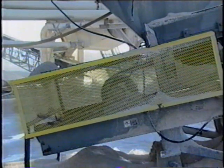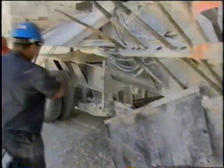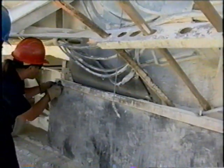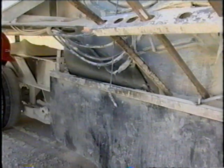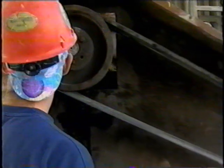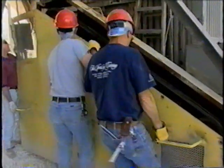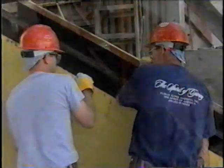Guards protect workers from exposure to moving machine parts. Serious injury can occur if guards are not in place. Look to see if guards are missing on moving mechanical parts, if coverage of existing guards is not adequate, or if there is no area guarding at all. What is the condition of the guard, and is it securely attached?